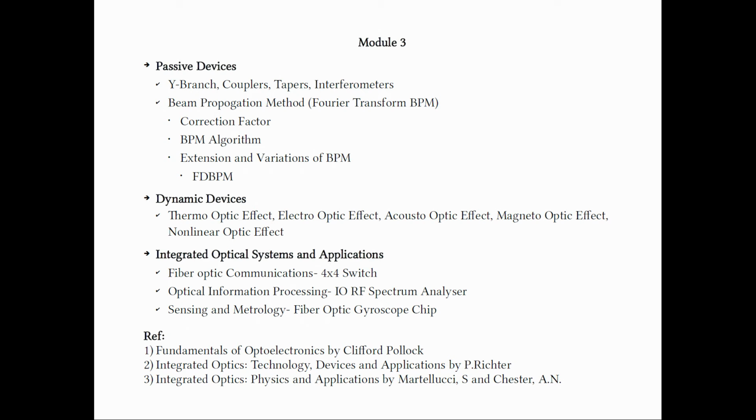So, the electro-optic effect could be used to make many other devices like optical switches. For example, we can take a directional coupler switch and then apply the voltage to make it into a bar state. So, you can switch between the crossover and bar state by using this electro-optic effect. And also we noted later on that we can have higher order devices by cascading these unit devices.